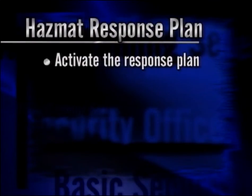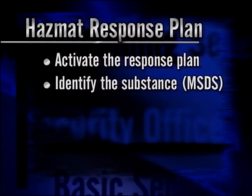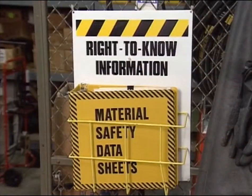First, activate the response plan that is part of your manual. Get the wheels rolling, as this is important and you need to do it as soon as possible. Time is a critical factor in a good response. Try to identify the substance that's been released. Check the transportation placards, shipping papers, inventory lists, anything you can find that will tell you what you're dealing with. Once you know, you can check the material safety data sheet in order to get more information about the substance and how to handle it.